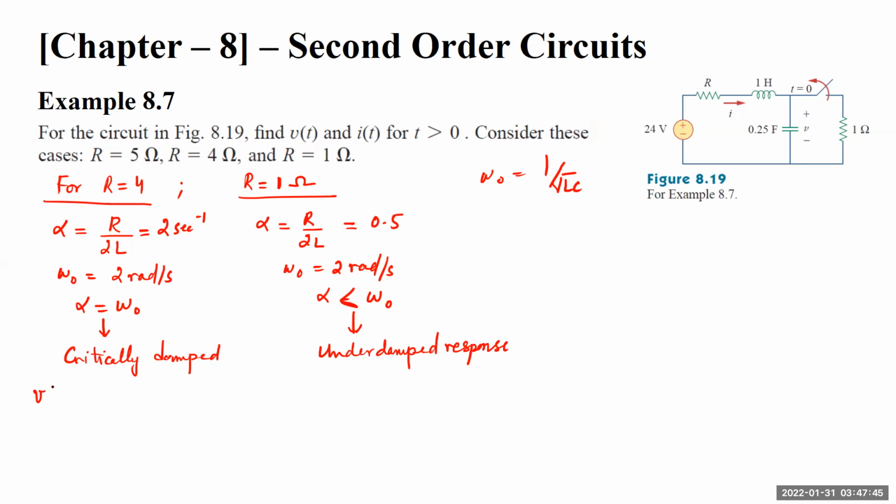So in this one, we will have v of t equal to Vs plus, for the critically damped response, my equation looked like (A1 + A2 t) e raised to the power st. This is how my equation looked. And for this case, the overall response is steady state Vs plus, remember, this is where we have the imaginary part of the solution in the characteristic equation coming up.